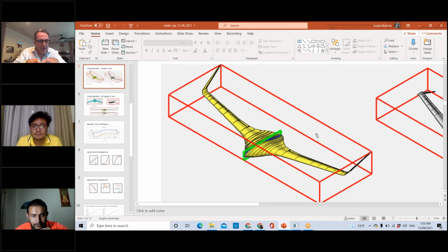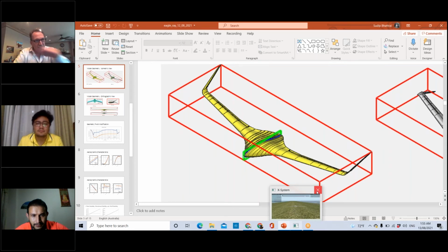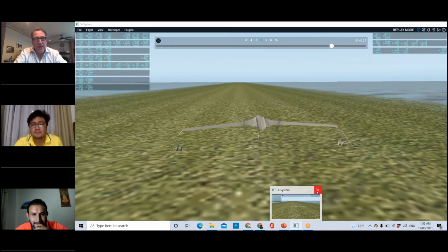Sometimes when you have payloads underneath the airplane, it's kind of nice to have side area to work with, if you want to look sideways, or put in a payload that's not just down. So I often make the top continuous as opposed to having a hump in the middle. But both work fine. And you may find that you can straighten up the trailing edge a little bit by shearing the middle up.